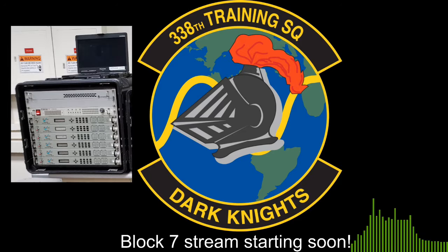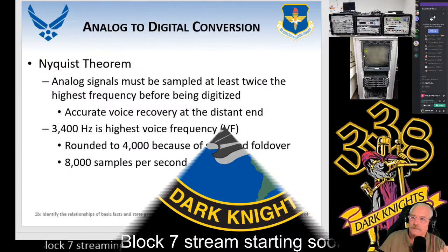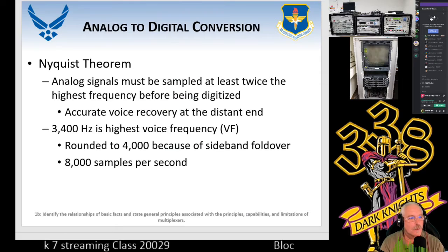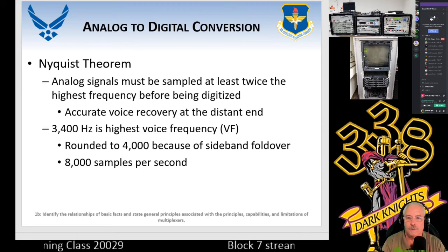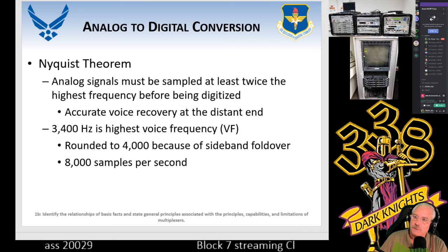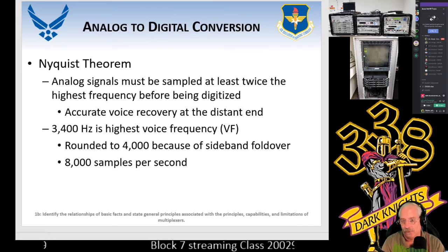So let's get right to it. We're going to start where we left off, which is the Nyquist Theorem. Again, 2 times the highest audio. In our case, it's going to be 4K. The reason why 4K is we're going to double that. That's the way PCM is. And we were explaining Audacity before Aaron Bridges had to leave.